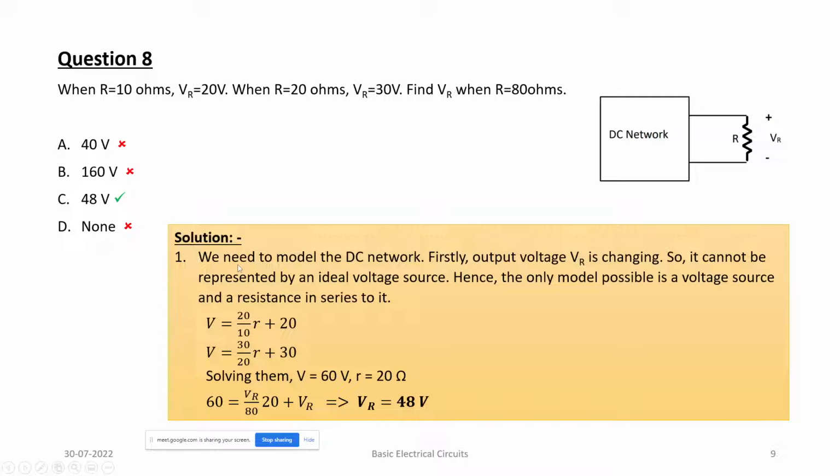No sir, it's clear. It's basically V equals IR plus this VR, the current into the series resistance, plus the VR. Okay, this part is not resistance, it's voltage equals voltage only. Basic KVL is being done. The small r is provided as capital R in the diagram, sir, is that correct? No, capital R is the load resistance. The small r is the series resistance that we are modeling, which is there in the network.